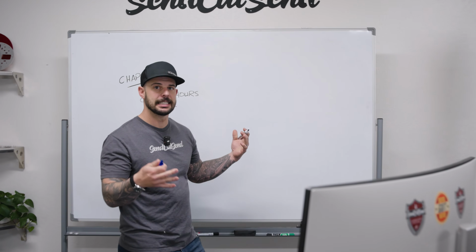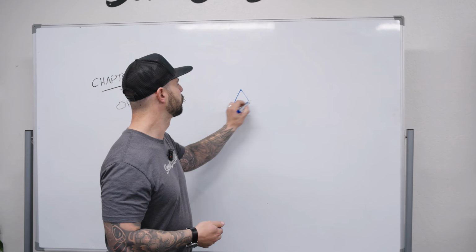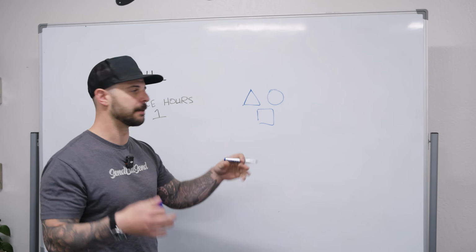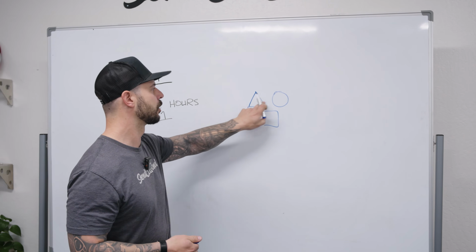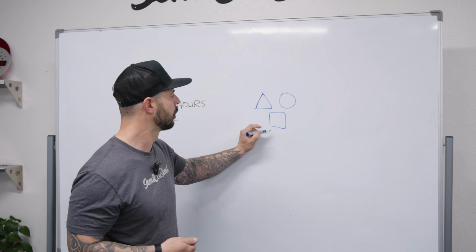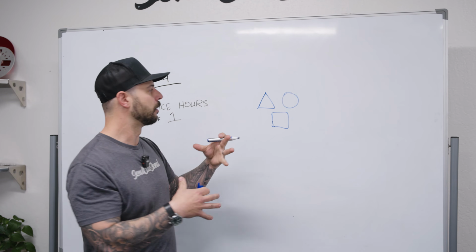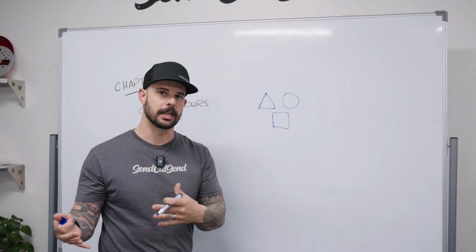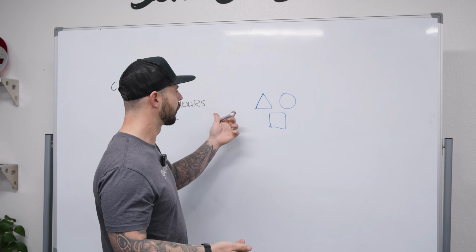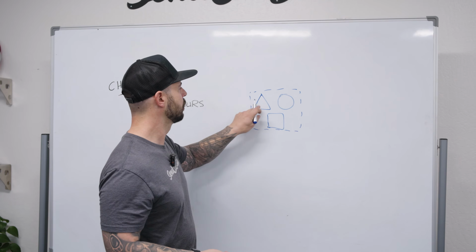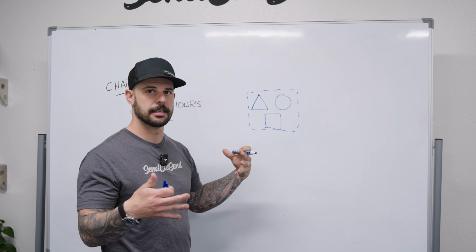If I have a nested DXF, I would have multiple parts in the same file type, or DXF. I would have a triangle, circle, or rectangular square here. These are individual parts, but they're all together in that one file. Now, there's two main reasons that you don't want to do this. The first one is that the overall outside dimension is going to be that nest dimension.